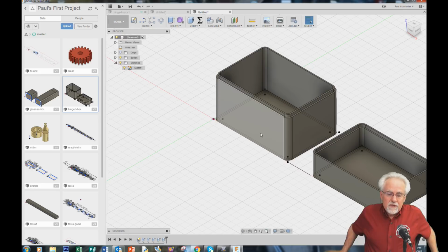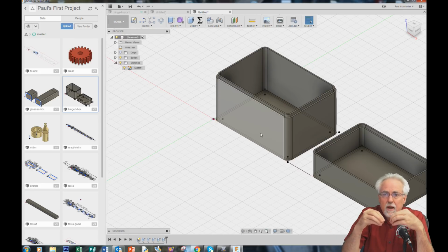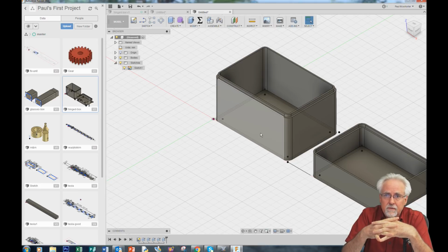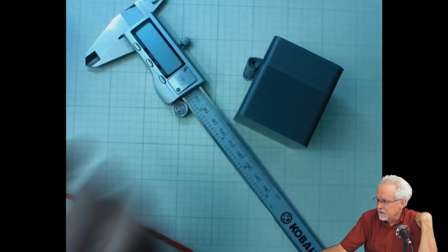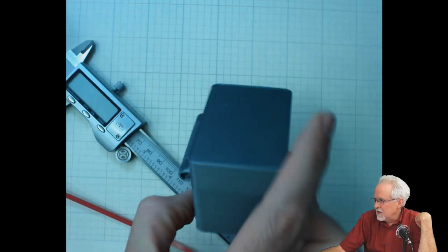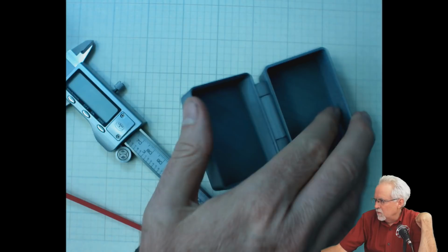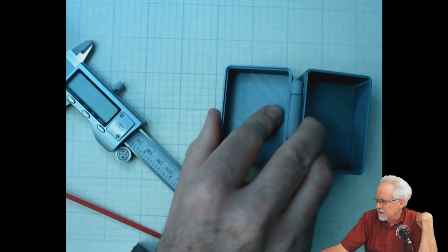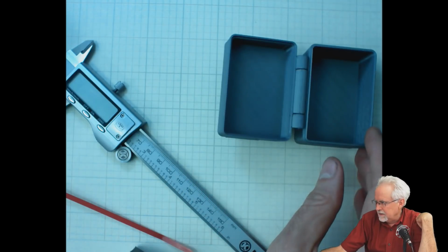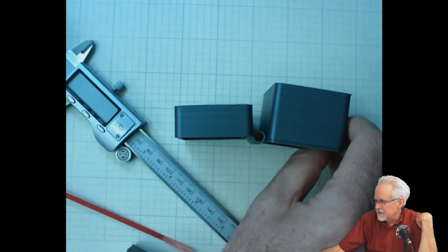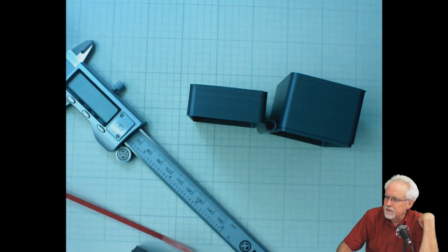Now, normally in the sketch you want to go in and start playing with your parameters and make sure that they don't break, and so we will do that on the next part, okay? But we're getting now ready to deal with, now is when the rubber really meets the road, because we're going to have to deal with the hinge. We've been working like this, but you see, I can't sketch in my old friend the XY plane anymore, because I'm going to have to sketch like this, and I'm going to have to do an extrusion, all right?